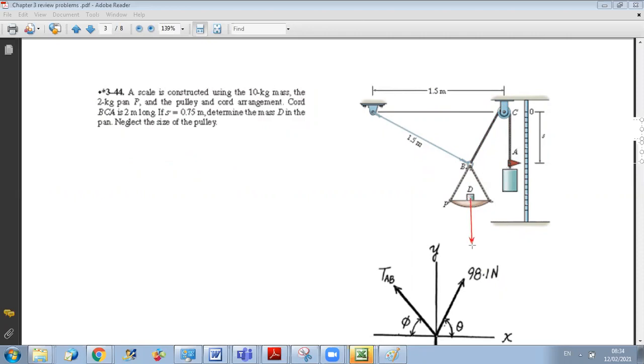Okay, and W total is in equilibrium due to the tension in these two cables. These two tensions can have a resultant force, which will be opposing the weight. So if you want by action reaction, this cable is attached to B. So what will be the total action on B? The total action on B will be this force T1, but downward, and force T2 downward. So the summation of these two forces will give you what? It is the weight. This is why I directly put the weight here.